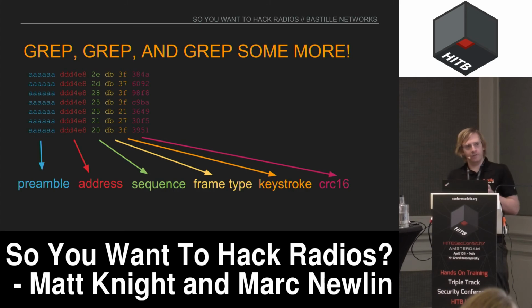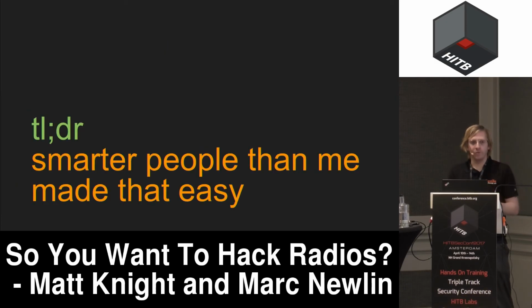Now what's kind of fun here is we've barely touched a radio. We haven't written any code outside of dragging and dropping some stuff onto a GNU Radio flow graph, and it's allowed us to go from knowing nothing about the device to knowing exactly what the packet format is that it sends over the air. And this is because people much smarter than me have built out this great ecosystem of tools to make it possible to leverage open source intelligence and these open source tools to really get away from all the radio stuff and treat it like a normal software reversing problem.